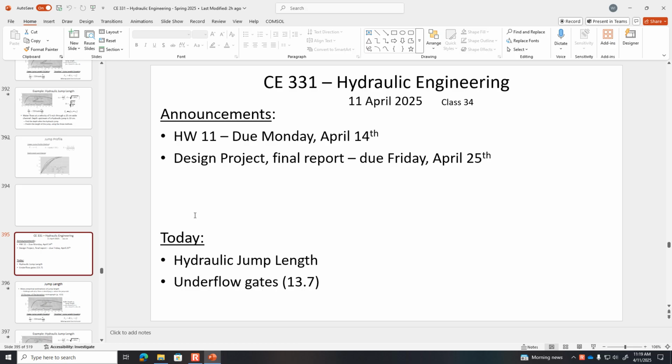So kind of the rule of thumb, or what I've observed in the lab, is that it's about a third the distance where we would see the critical depth. So there's a period where it's a little bit higher than the flow over the obstacle, where it's accelerating, and then it achieves critical, and then it's getting shallower and shallower as it approaches that drop-off.